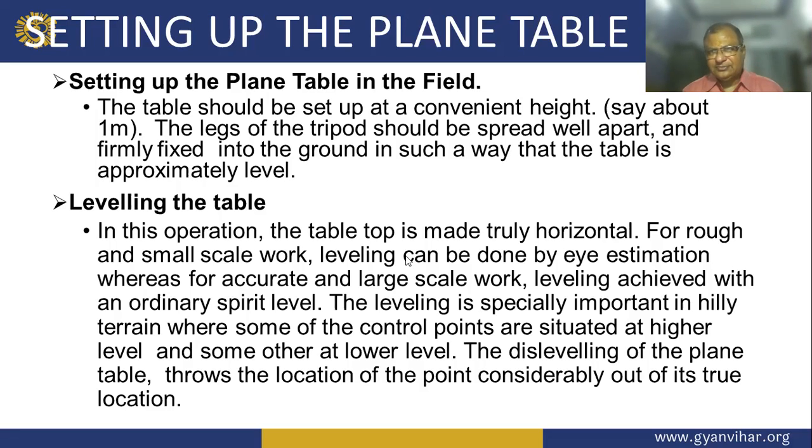Leveling the table. In this operation, the tabletop is made truly horizontal. For rough and small scale work, leveling can be done by estimation, whereas for accurate and large scale work, leveling is achieved with the ordinary spirit level.